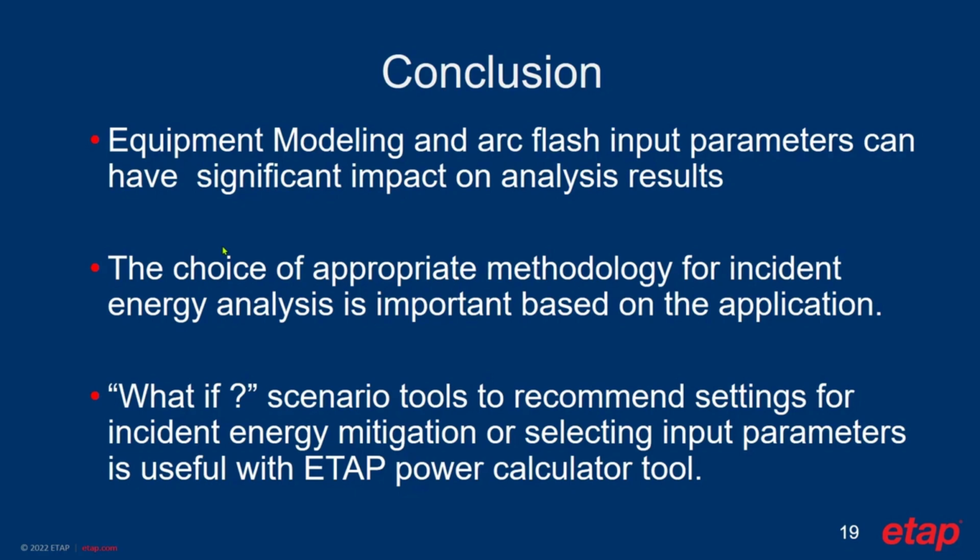And on top of that, for selecting the gap between the conductors on a DC equipment where equipment access or measurements are not possible, the Stokes and Oppenlander method was used to estimate the gap between the conductors for this particular location where the maximum power method cannot be used.